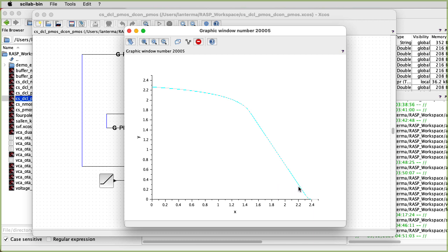That corresponds to a range of 0.6 volts. And the outputs that we get in that region look like they're around 1.5 to something like 0.3 volts. So that's something like 1.2 volts. Okay, so that would be like a slope of -2.